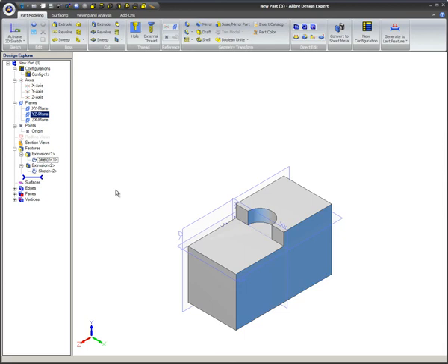Note, when using extrude features, either boss or cut, it's possible to add material where there is already material, and also to cut air. Both of these situations can allow you to create features that seem not to appear in the workspace window but are actually created. To verify that the feature has actually been created, you can look in the Design Explorer and see the feature.